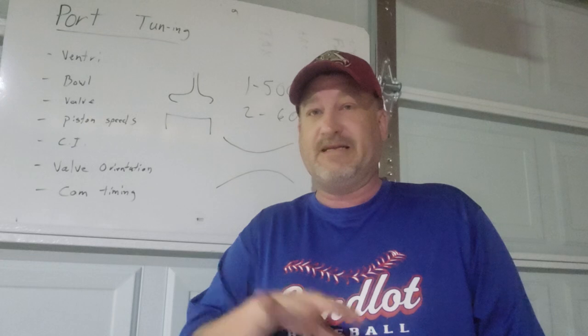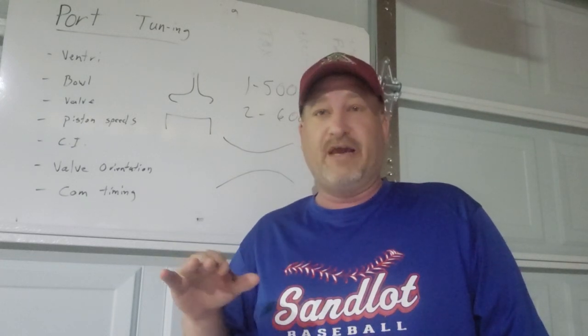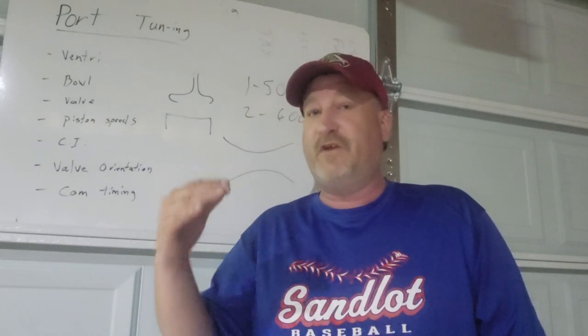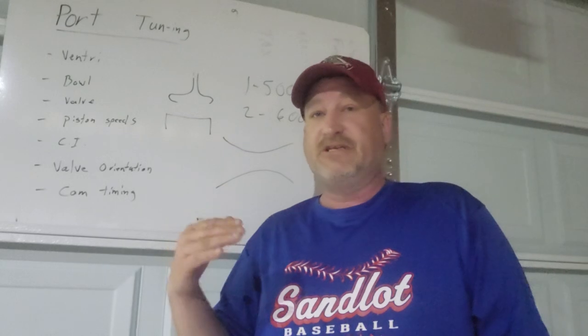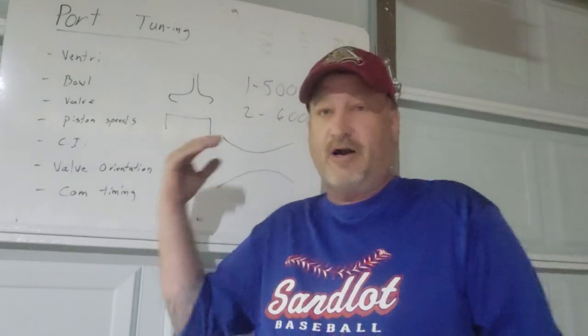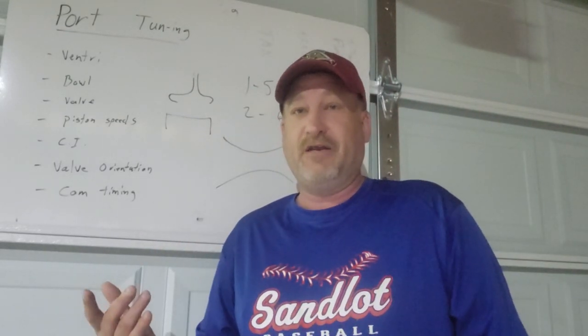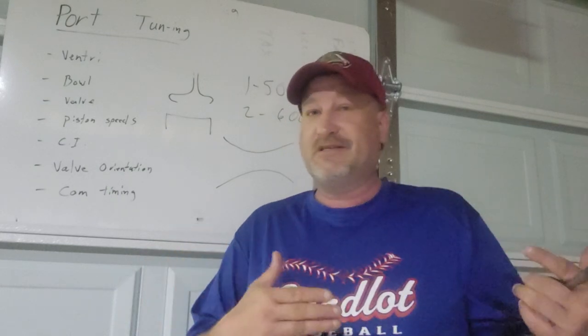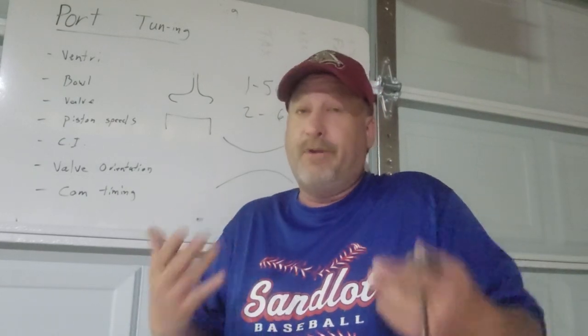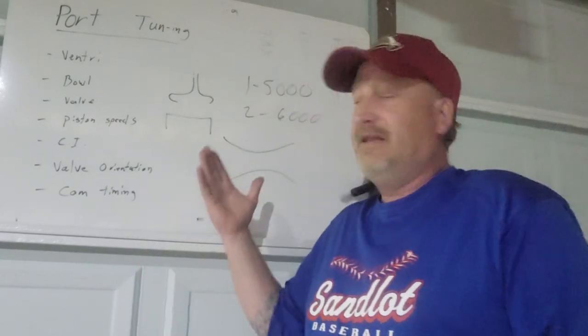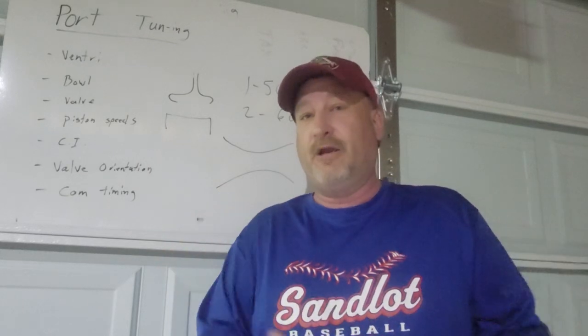The computer technology can control that to the point where the most efficient port tuning is achieved no matter where in the RPM range the engine is spinning. With the older engines, it had to be the individual builder designing the engine around its intended RPM range.